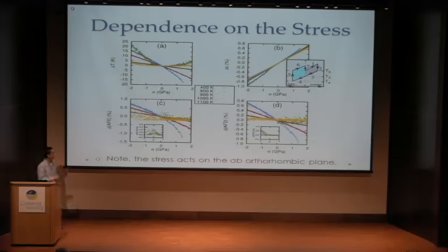Why this is very important: strictly under tensile stress, we have this negative change in temperature, so our change in temperature depends on the nature of the stress. On the inset of figure B, we have a basic refrigeration cycle. If we start from an initial temperature in the antiferroelectric phase, we can adiabatically apply compressive stress, which gives a positive change in temperature.